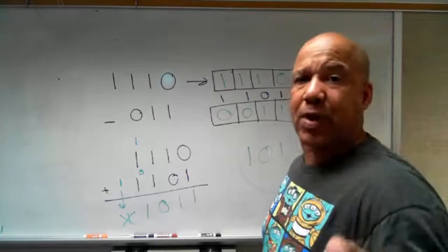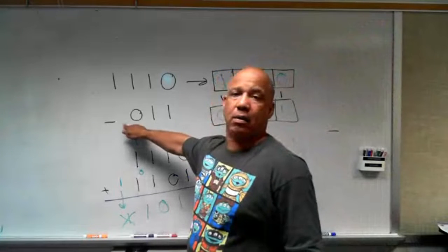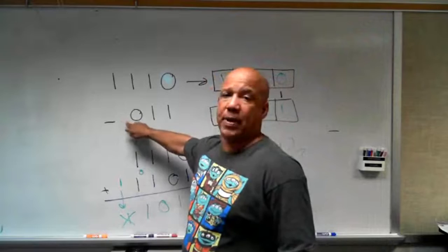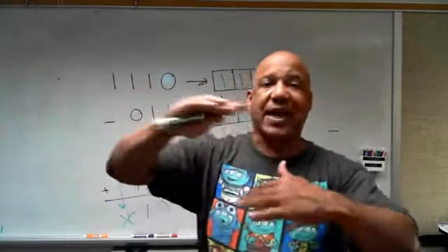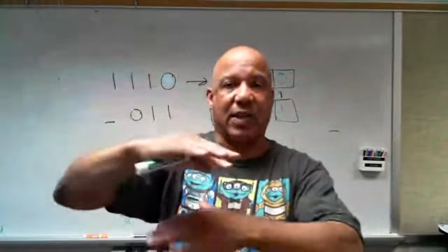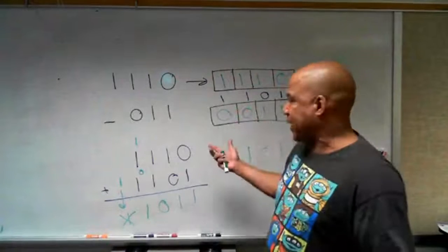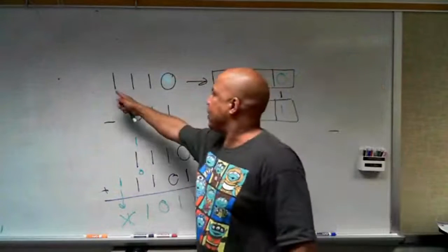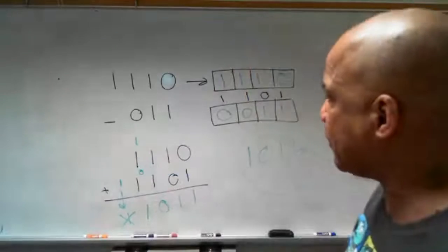But you raise a fair point. There should have been a 0 here. And if you try on the 3-bit number, it won't work. When you're doing this two's complement, the machine is actually using shift registers to hold the numbers, and then the logic is doing the actual math. So you've got to have the same number of cells in the register, which means the numbers you're adding or subtracting have to have the same number of binary digits in them. So that's a good point.